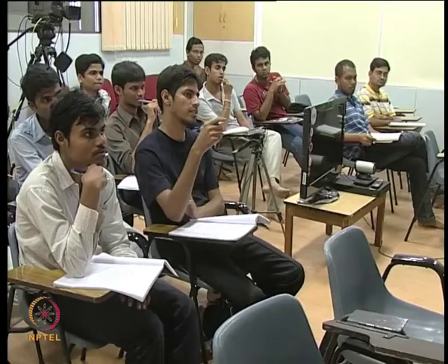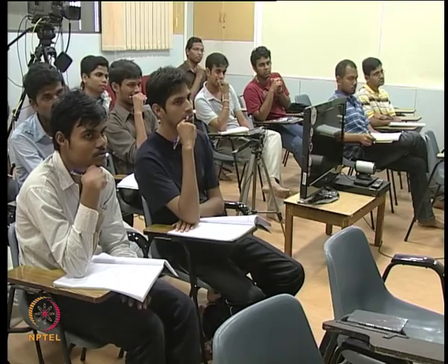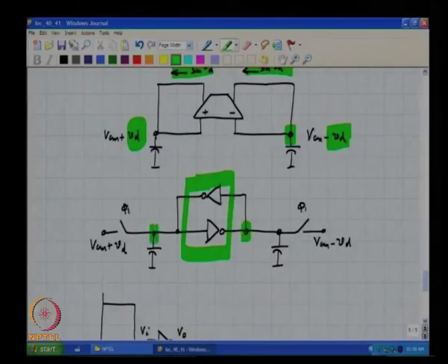This will be trying to write some value, but that inverter output will be pulling up. Correct. So, basically these will be pushing currents into these two nodes which are dependent on VD of t, which is not yet settled to the right value that you want to make a decision on.